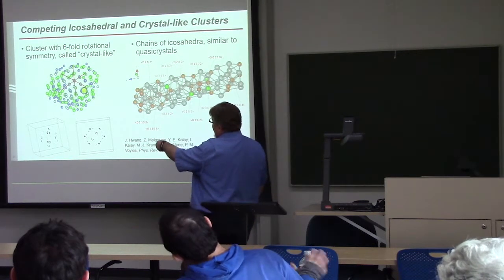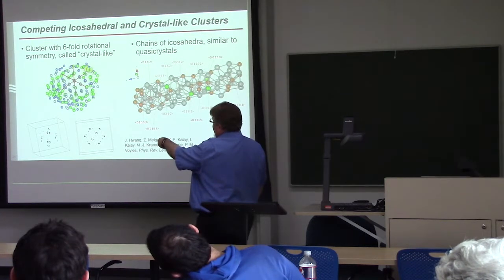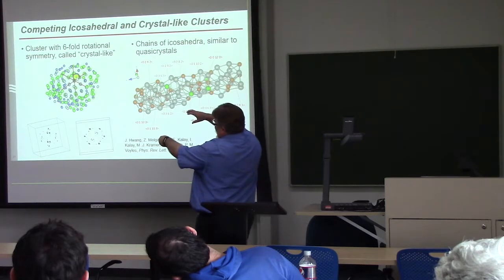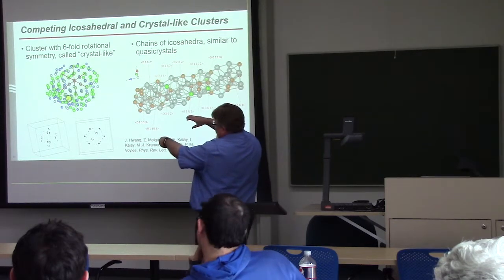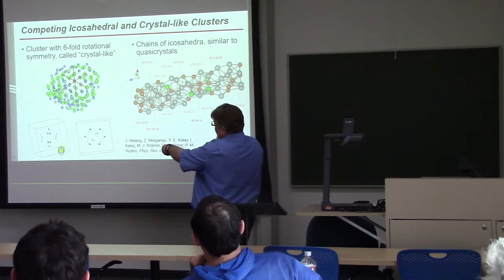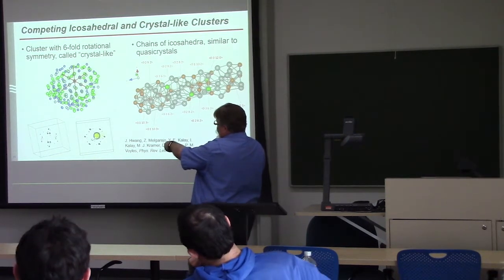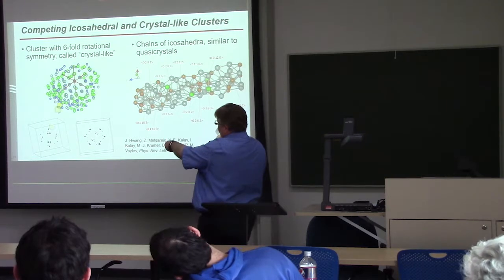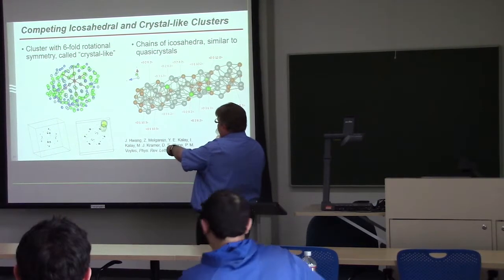Here's a chunk of a model of a zirconium copper aluminum metallic glass oriented down one of the six-fold axes for this ordered region. Here are computed views of the reciprocal space for the model showing the six-fold ring.